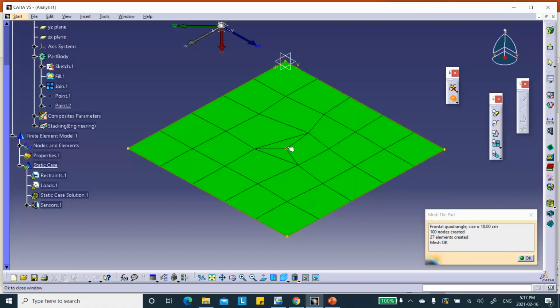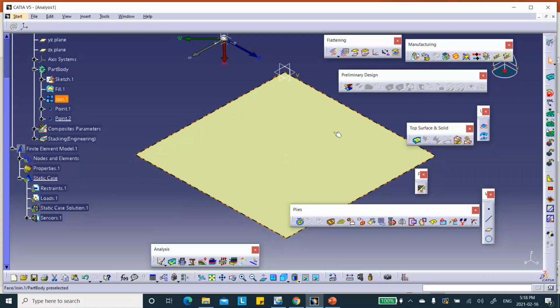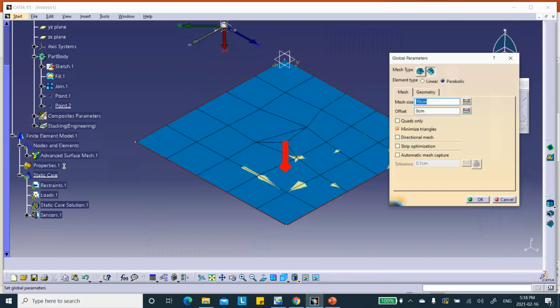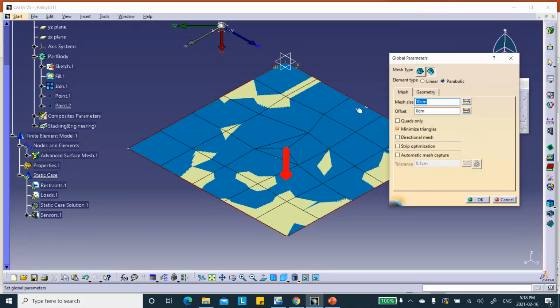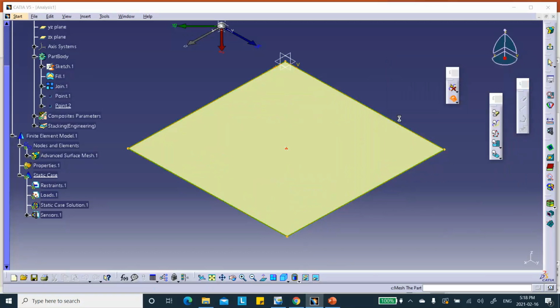Okay, now this is an ugly mesh, and I understand that, and you can work on this thing and get it to make it look better, etc. As a matter of fact, let's try to make it look better. Cancel that. Let's double click on this guy again. Let's go back here. Where's the mesh? Right there. Double click on this. Let's make this thing maybe, let me do the following. Let's do quad only. Okay, how about checking quad only? Okay, that's fine. And then mesh it.